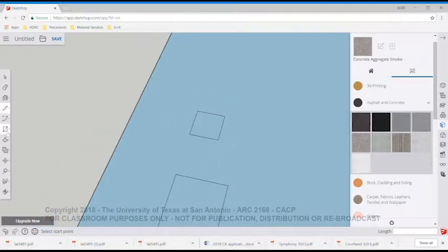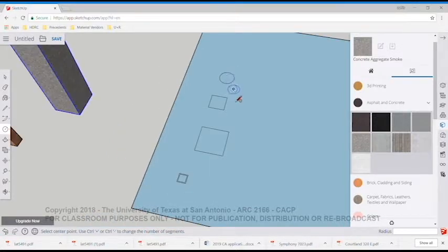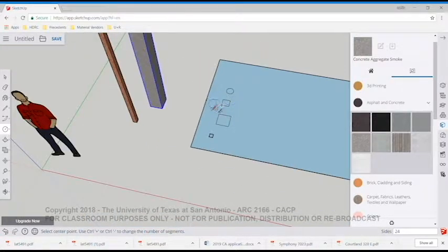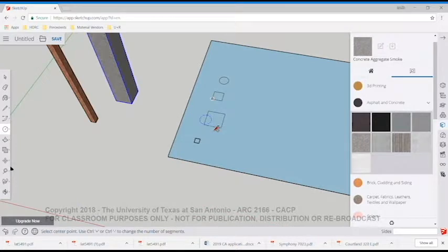Or I could do a pole barn type column, which could be round, and that would have about a 3-inch diameter. So those both could be wood columns. Could also do a concrete column, and the concrete column would need to maintain 10 inches across its face to contain that steel.